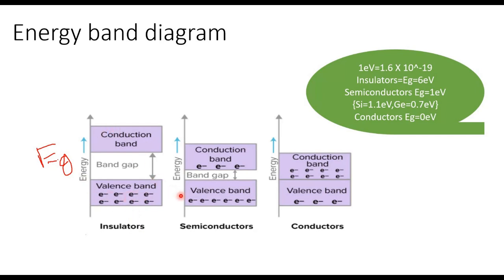conduction band. In a semiconductor, the forbidden energy gap between the valence band and the conduction band is very small, like about 1 electron volt as compared to the insulators. Therefore, a small electric field is required to push the free electrons from valence band to the conduction band. So as the temperature is increased, more valence electrons cross over the energy gap to reach the conduction band, and the conductivity increases. This shows that the electrical conductivity of the semiconductor increases. This means the resistance has been decreased.